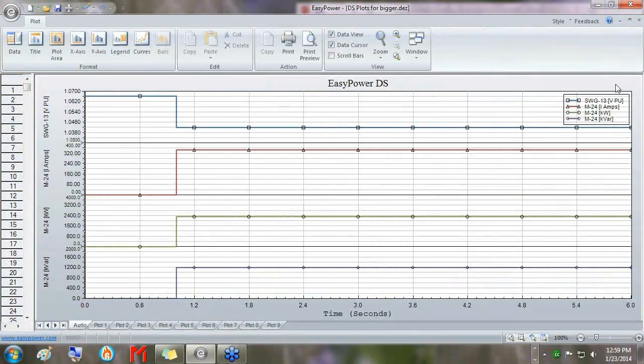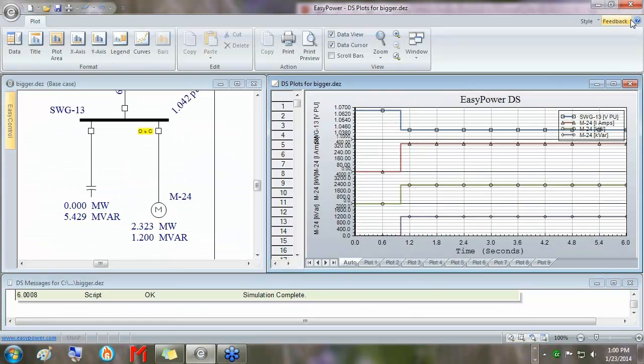notice that it's exactly what we have. We have no dynamics information. We see no rounded curves or anything because all we did was run steady state for 1 second and then throw the load of the motor back on, and we step up into that condition and continue on. So we went from offload to an onload condition. And so you can do any of these type of switching actions inside the dynamic stability focus without adding any dynamic stability data at all in any of your equipment.